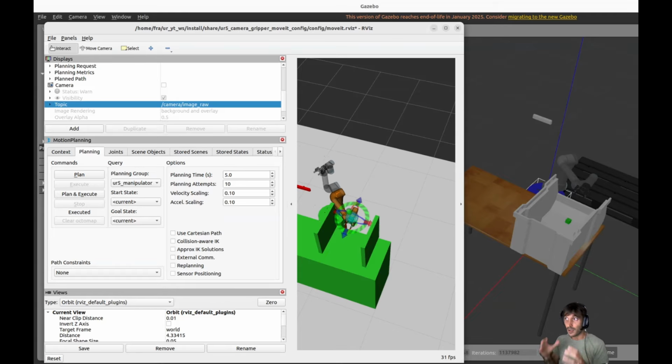Okay, and this is very useful if you have some objects that are dynamically changing over time. But if you're gonna have some objects that are static with respect to the base link, most likely you're gonna have this kind of scenario in an industrial application, then I would suggest you save some computational effort from your machine and code a hard-coded collision object into your inverse kinematics algorithm.